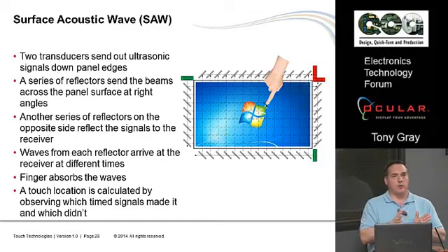And the time for each of those waves is different, the traversal time. So your controller can then basically figure out, I have 20 waves, they occur at these particular time frames. When I have a finger in the way, I miss one of those time frames, or 2 or 3 of those time frames. So now I can go through and say, okay, I had a missing time frame here, and a missing time frame there, and if I put those two together, I get an X and a Y coordinate.